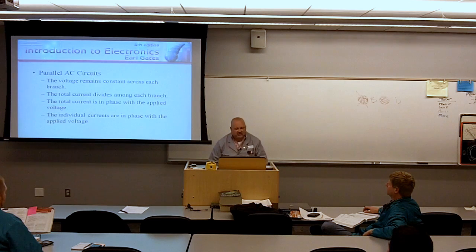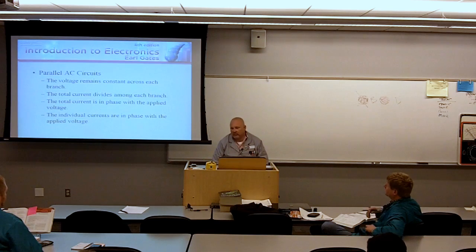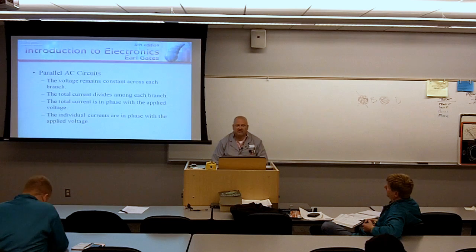Parallel AC circuit, just like a DC circuit, the most important thing to remember is that in parallel, voltage remains constant across a parallel network. Another term for a parallel circuit is a current divider. So total current divides among each branch. The total current is in phase with the applied voltage. The individual currents are in phase with the applied voltage, because it's purely resistive.